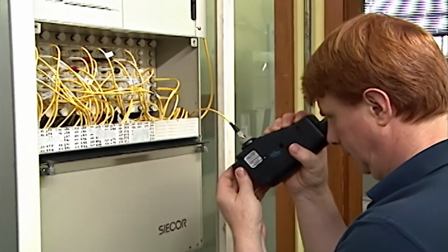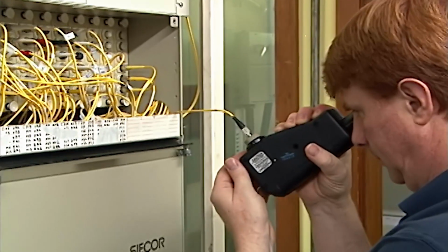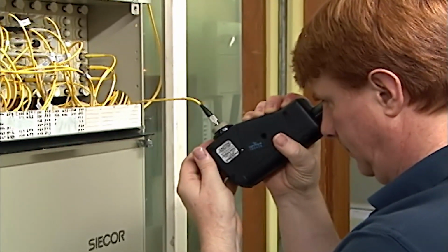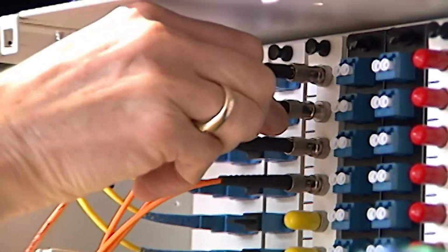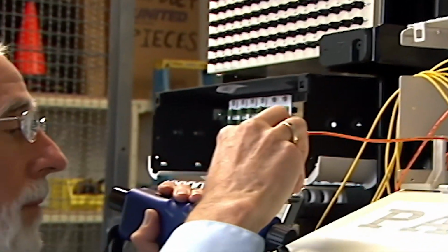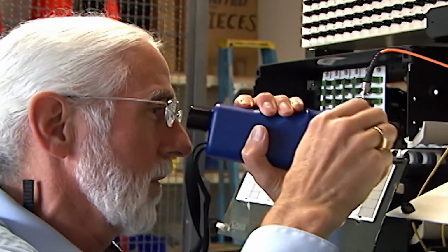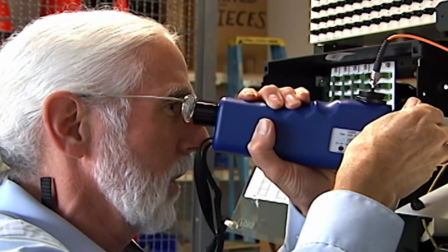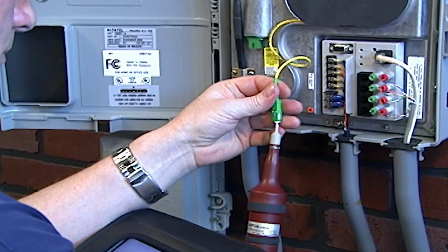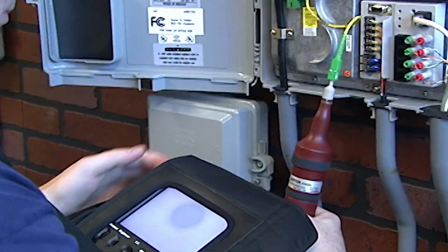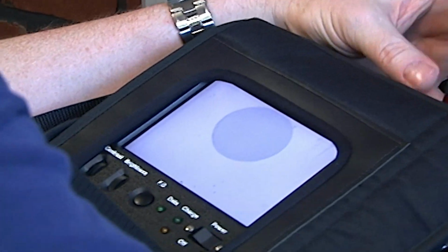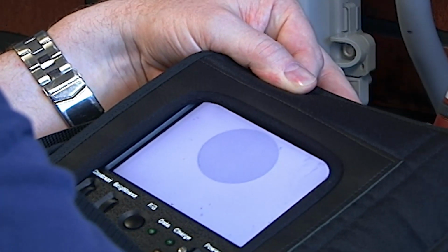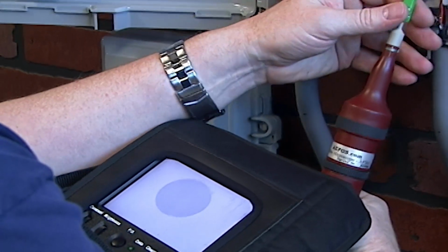Scopes are most commonly available with 200 or 400 power magnifications. The 200 power scope can show sufficient detail when inspecting multi-mode connectors. However, when testing single-mode connectors, the use of scopes with 400 power or greater is recommended. There are also a number of video-based inspection scopes available. These scopes can be safer to use than their optical counterparts. Because the operator is looking at an LCD screen and not the fiber itself, there is no chance for a stray laser beam to enter the eye if the fiber system is live.